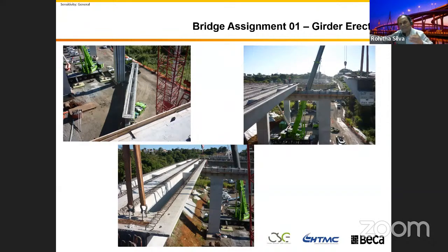The span of the bridge is always greater than the width of the creek, 30 plus clearance requirement, the thickness of the column plus some spacing for foundation. That is another obvious reason. There's a standard practice in the construction, 1.5 and 1.8. That is the cost differential we're going to look at in there.